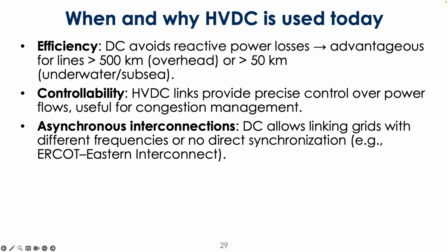So every single spinning generator west of the Mississippi is spinning in such a way that they're essentially lined up with this frequency, right? And as you fluctuate this particular frequency, that's going to affect every generator on our electricity system slightly, right?